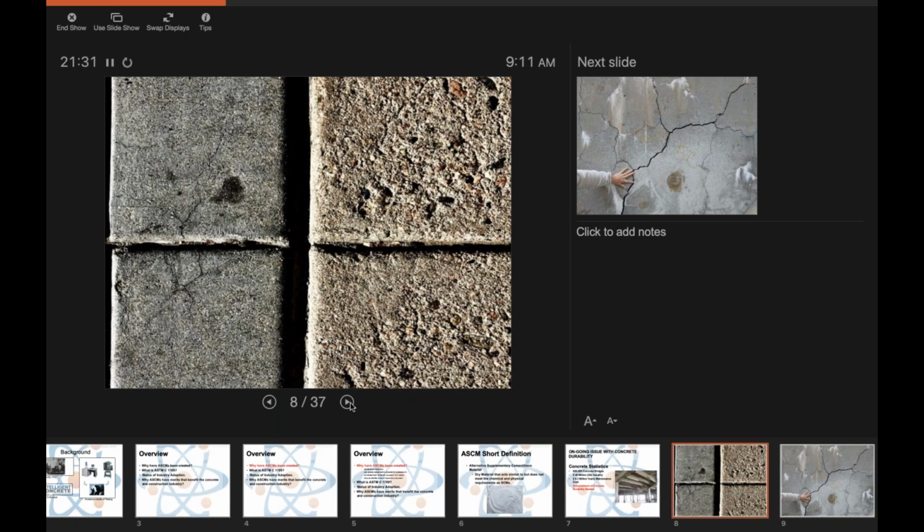We have folks who work for us in a subdivision, and there's mag chloride all over the place, and that concrete is falling apart within the first season. This is what one season on the left looks like, and two seasons on the right. That's just something we as an industry have been willing to accept, because we either don't have the high quality materials, or we just don't have enough of even low quality materials. I'm talking about, for us here in the Midwest, Class F fly ash.